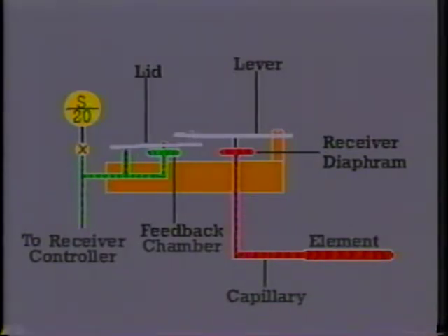Once the transmission line is filled up, back pressure fills up the negative feedback diaphragm, which results in an upward force. This upward force will raise the lid off of the control port slightly to stabilize the transmission pressure. This negative feedback feature is characteristic of all pneumatic proportional devices.